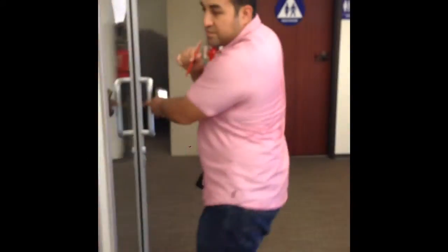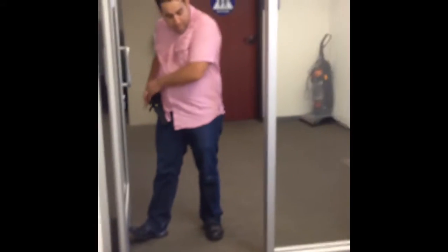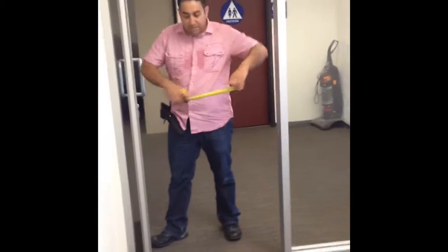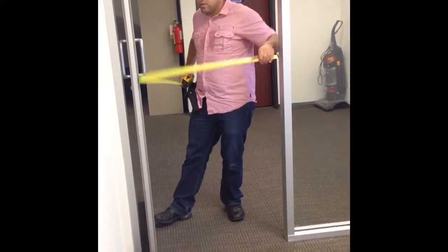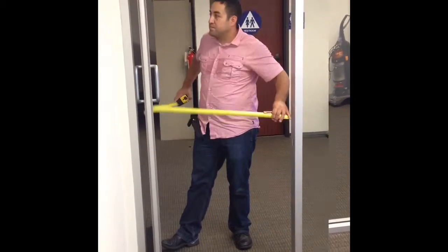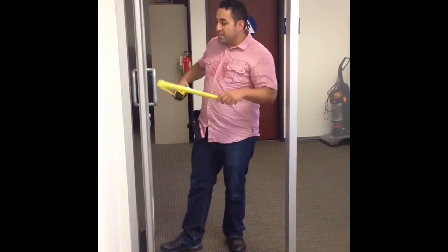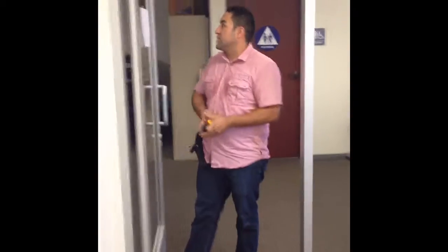We're going to take the clear door dimension by measuring from the inside face of the jamb to the door. So we'll write that dimension in as the clear dimension.